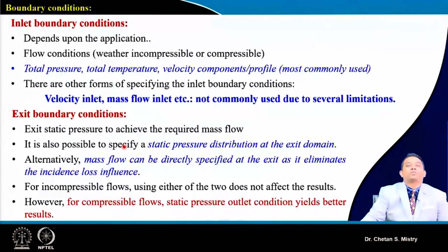You need to say this is my inlet, and at the inlet we need to put certain flow parameters. So based on what kind of application we have, we need to give the inlet boundary condition. The flow conditions basically: is it compressible flow or incompressible flow?